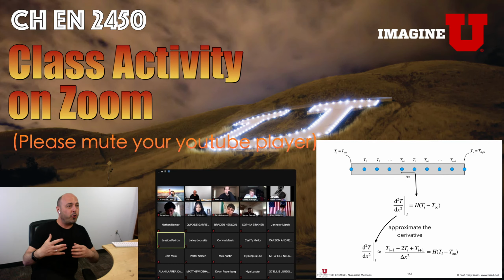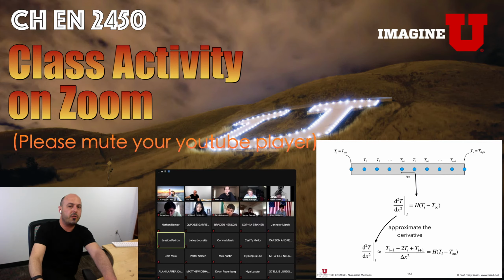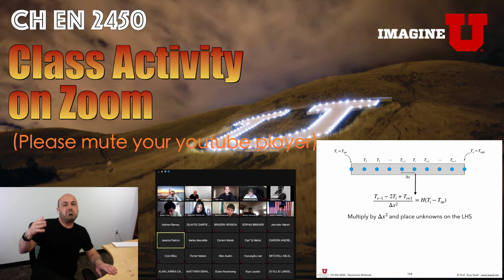Turns out the formula, in this case, is the equation at each point, and we're going to put them all together and solve them together. And that formula is discretizing the second derivative. So now you see how we've built a relation at an arbitrary point i. We built a relation between Ti minus 1, Ti, and Ti plus 1.